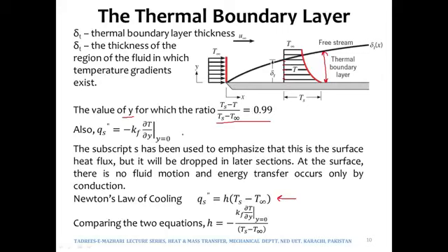If we compare these two expressions, because the heat transferred initially from the surface to the first layer of the fluid will further be transferred to the subsequent layers via convection, if the system is working under steady state conditions, then we can write the expression of h as minus K times ∂T/∂y over Ts minus T infinity.